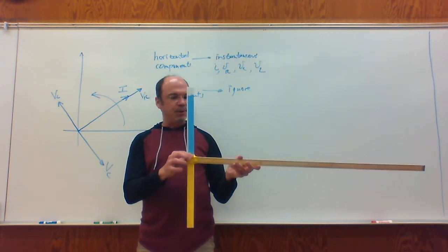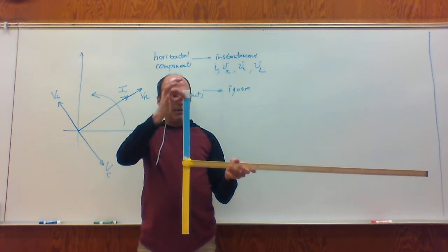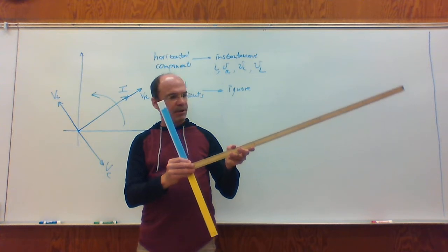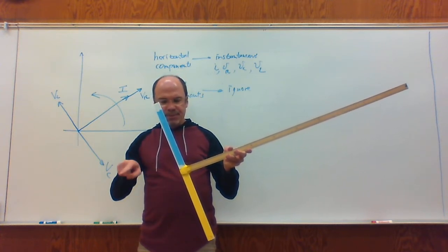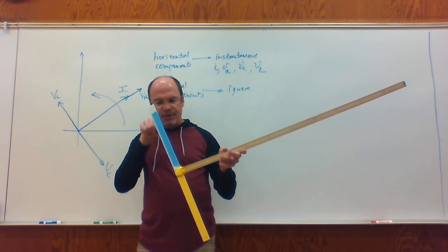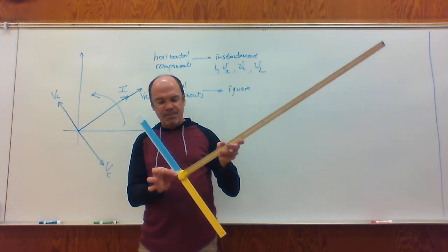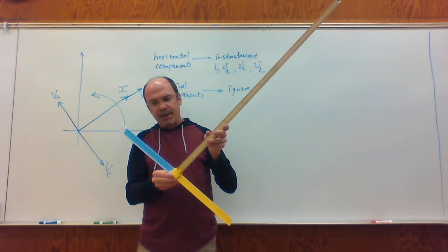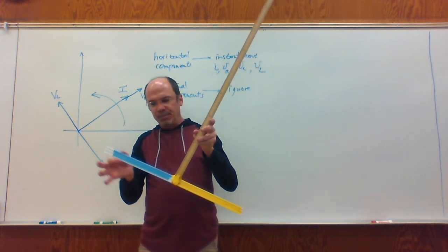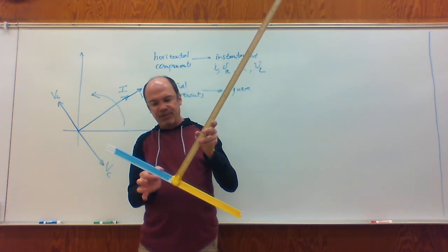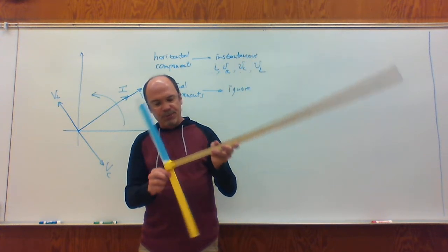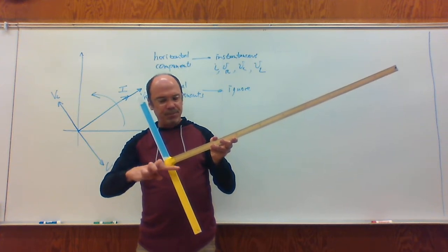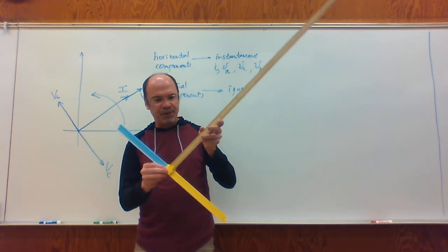What about the voltage across the inductor? The voltage across the inductor leads. So as the current gets smaller, the horizontal component of the voltage across the inductor gets more and more negative. So as the current approaches zero, the voltage across the inductor approaches its negative maximum. At the same time, the voltage across the capacitor starts at zero, and its horizontal component, which points this way, gets more and more positive.